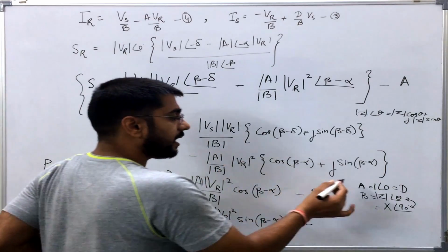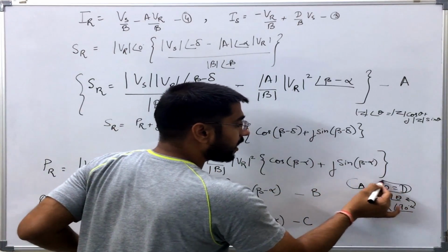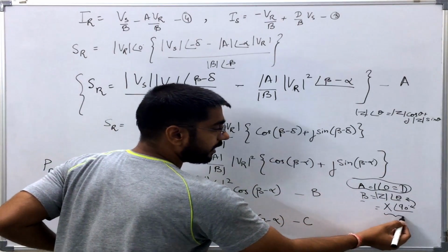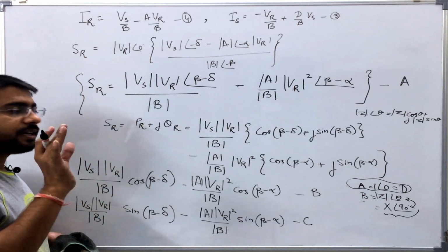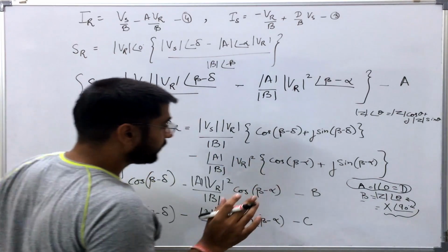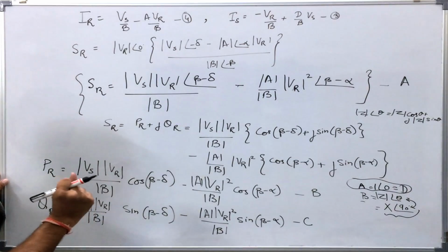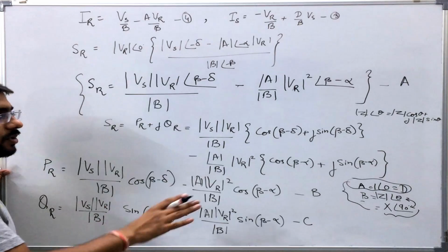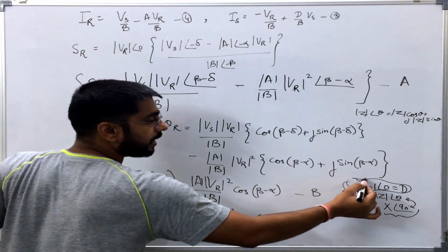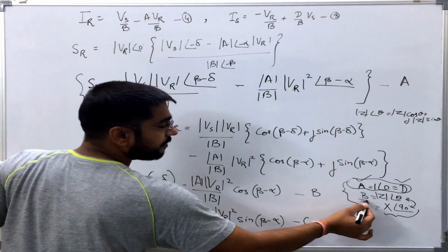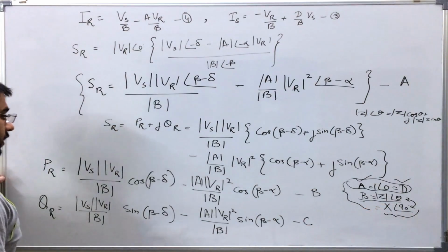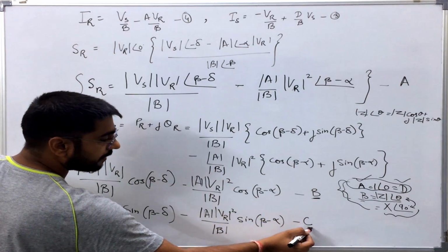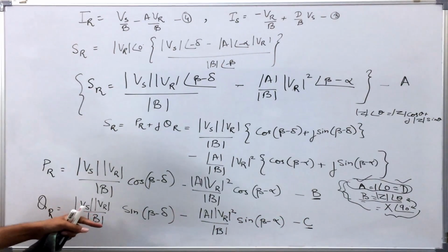So practically A and D are approximately equal to 1 and B is normally equal to the reactance of the line if I neglect various approximations. This form will be true for short lines, because for a short line A and D are equal to 1 and B is simply the impedance of the line.